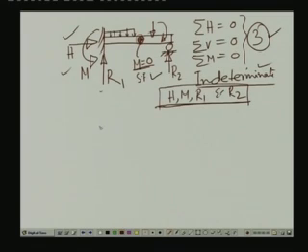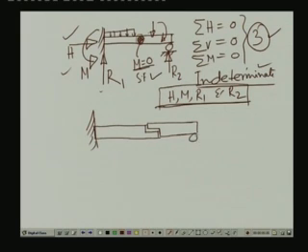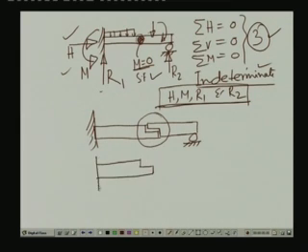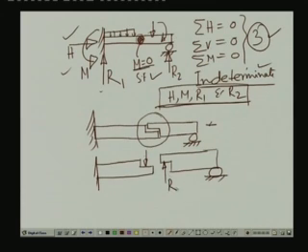If you look into this, this is the beam and the other part may be resting on this in this particular form. So, this particular part is fixed at this end, this is on roller. Now, at this particular support, if you split it into two parts, it will be like this: the reactive force from the top part, this is supported on roller at this end. Now, here we will have a reactive force, and here there will be another, and these forces are the same. If we call this R, this is also R, because this particular section can resist the shear force.